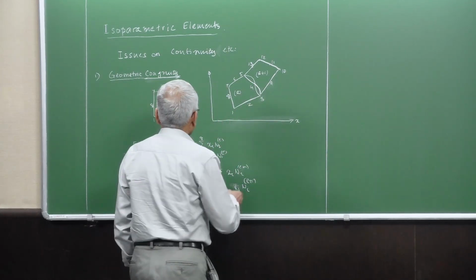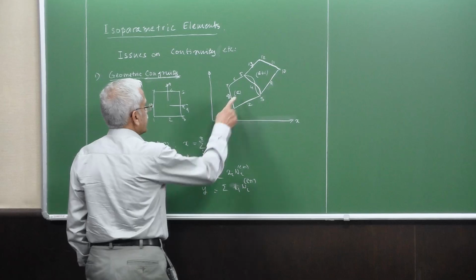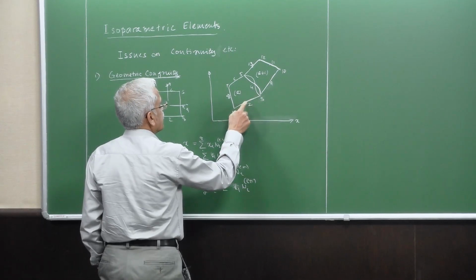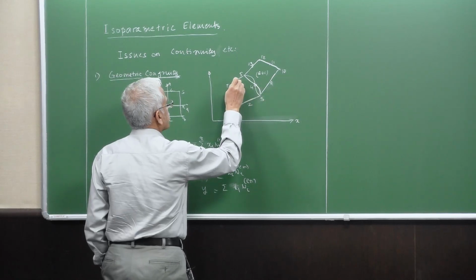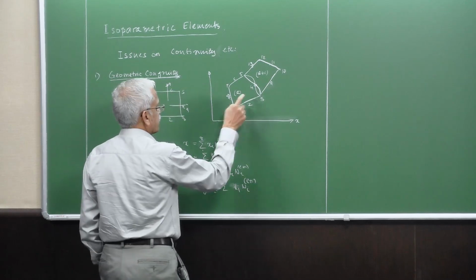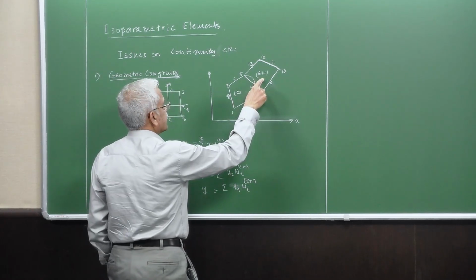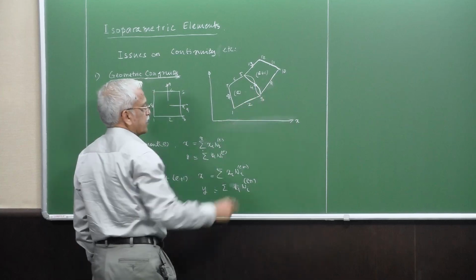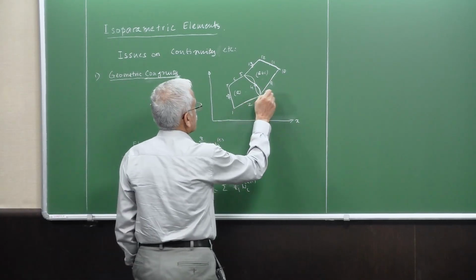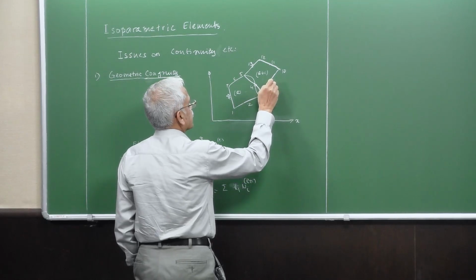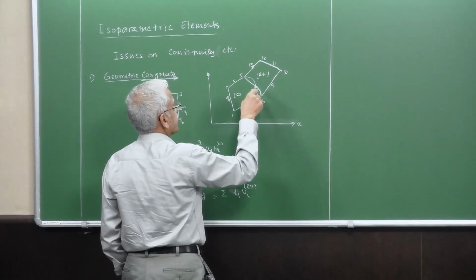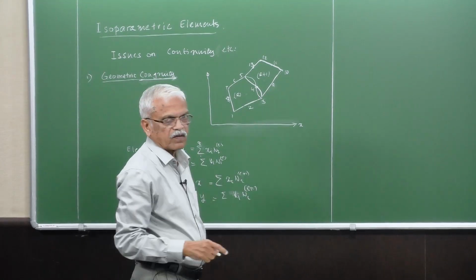So if you think that we are for element E here, using the coordinates of these 1, 2, 3, 4, 5, 6, 7, 8 nodes, this is the mapping of geometry from here. And as you show element E plus 1, you use the locations of these 8 nodes which are here, including these 4. So that means that these 3, 4, 5 are common.